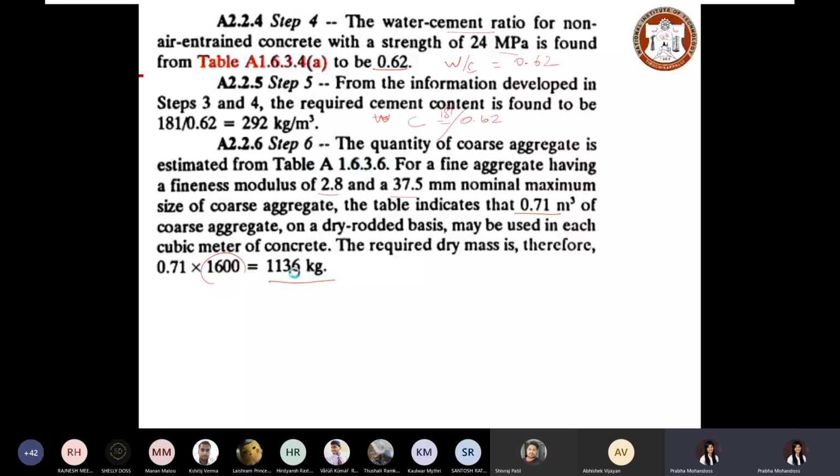And sometimes we keep 20% as a factor, so that we will have some excess amount of cement, in case it is required. Generally, when we do mix design and take weights for mixes, we consider 15 to 20% wastage, so that after wastage we will have enough material for filling the required samples.